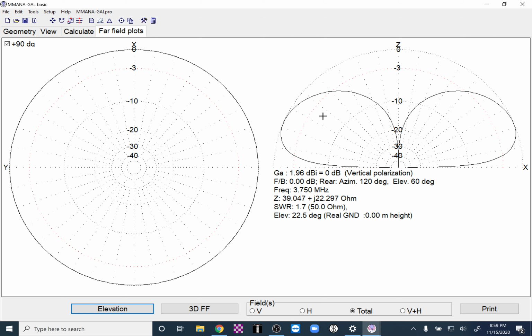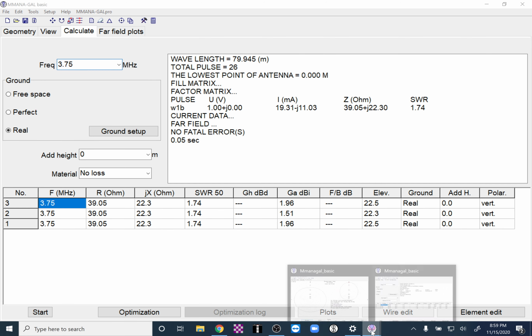So here's our radiation pattern. Obviously, since it's a vertical, we're looking at low angle radiation. For NVIS, we want our power going straight up. And if we look, we have a null going straight up. This would be a very poor NVIS antenna. This would be good for DX, or pretty much a DX antenna, or if you want to talk to someone further out on the edges of East or West Coast US from the central. Really don't know what else needs to be said about that.